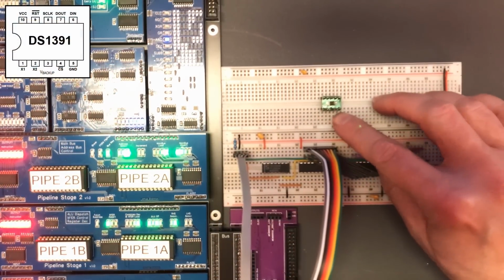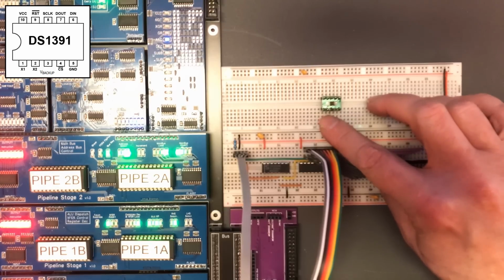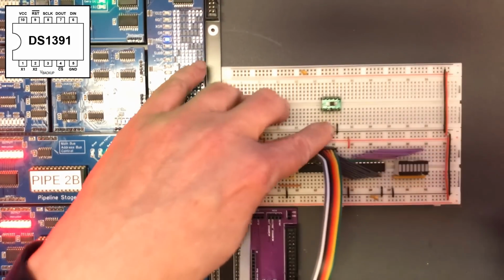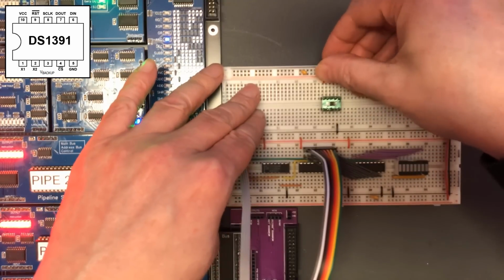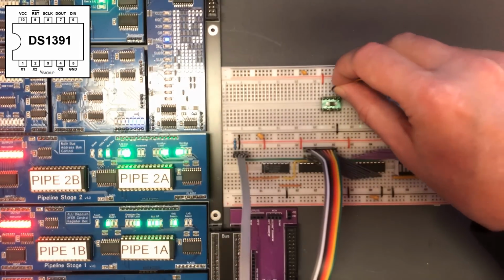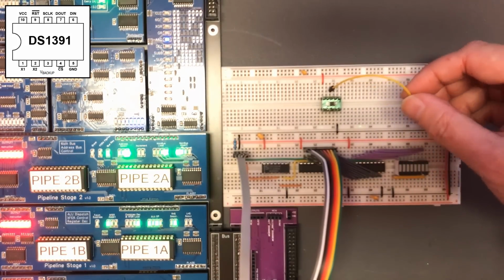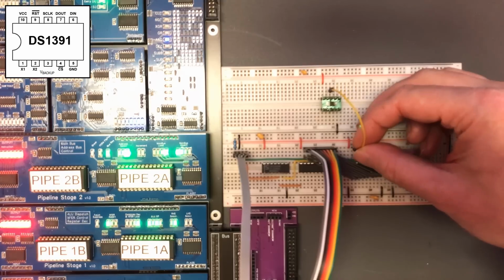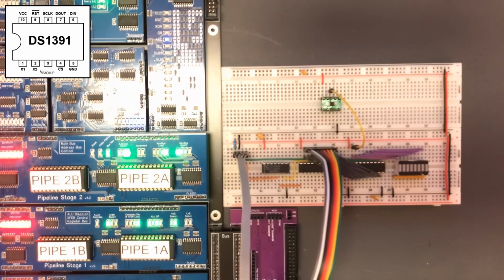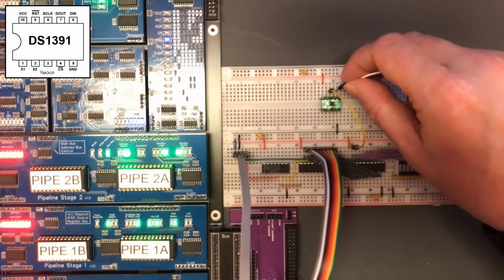Okay, I've orientated this the way we normally would for a DIP chip. So we can do the ground line and the power line. Now, clock is a pretty important line. That needs to be an output, and I'm going to take the most significant bit of our GPIO, just because the bit at the top and the bit at the bottom are the easiest ones to manipulate using shift instructions.